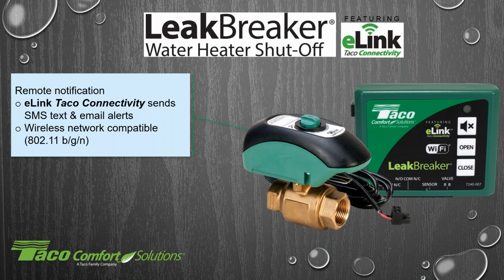And that CV32, as you said, means at 32 gallons a minute, that valve will impart 1 PSI worth of pressure drop on the fluid, which is kind of a speed bump in the big picture. Exactly, exactly right. Yep.